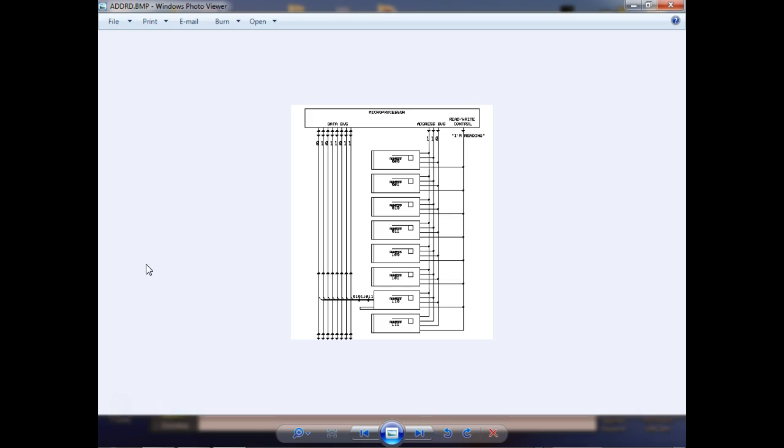These are connected all the time, by the way. It's just that only one of them is going to have the door. So what we do is we put a binary address out there. Well, binary address goes up the wall, the address bus. We have a special circuit out here called an address decoder. And all that guy is just sitting there looking at the address bus.